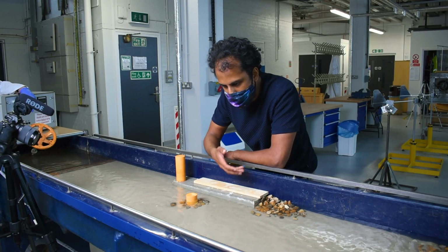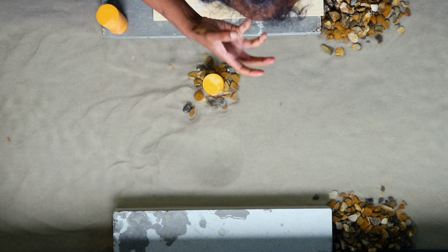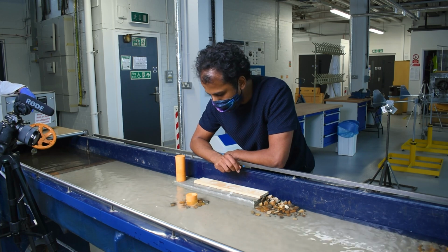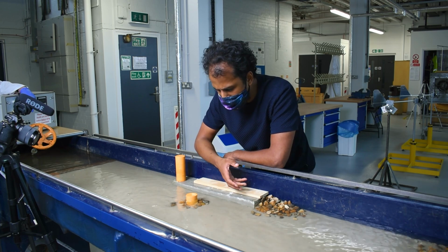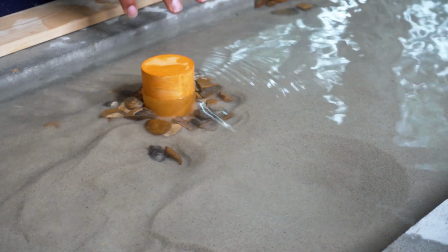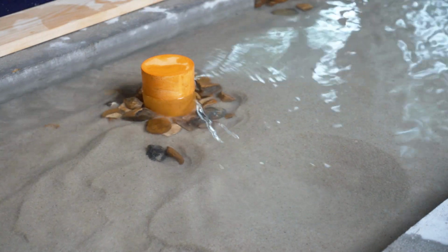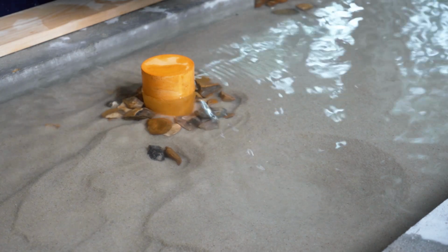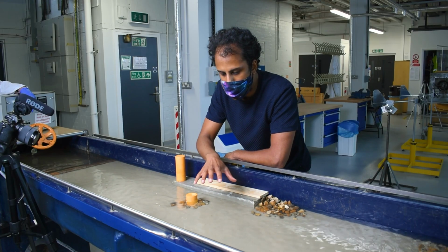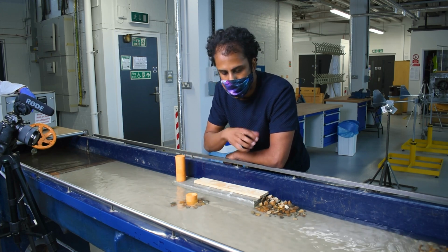So the flow is still separating off these surfaces, but the stones themselves are much heavier objects. So we often call this armour stone. And so the flow of water, the acceleration of the flow, is not going to be large enough to move these armour stones. And they therefore protect the bed underneath it. Now usually you would have something called a geomat underneath, which is like a special mat to protect the sand, and then you put the stones on top, for example.